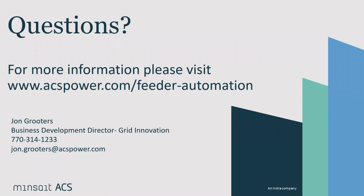Likewise, if you add a tie switch and add a circuit to an existing island, you simply need to go into the tool, select the new circuit that hasn't been used as part of that template, define the devices just like you did when you originally built the island, and again export and run that import process that builds a model, which takes only a few minutes. So it's a pretty simple process to make changes to an existing island, whether it be temporary or permanent.